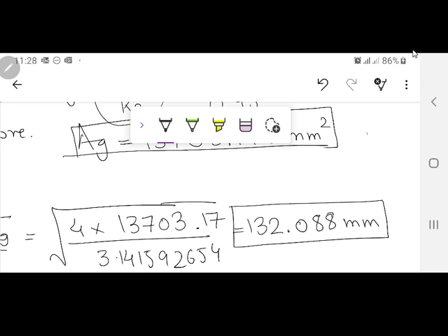Now here we will not do any approximation, please, very important, because this is in millimeters and you can cut with an accuracy of something like 0.1 or 0.2. That can be done. Now this is 0.88, I can call it 0.1 mm. It is totally up to the manufacturer who is cutting there. I will give this design. He cannot cut exactly up to 0.88, but he will certainly cut 0.1.